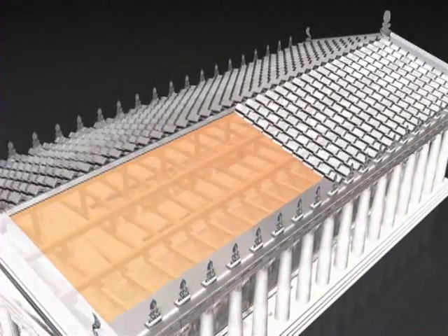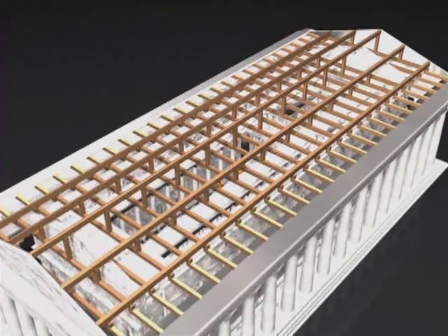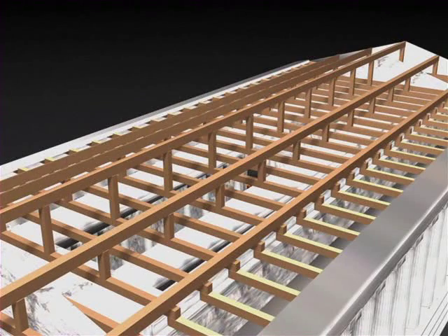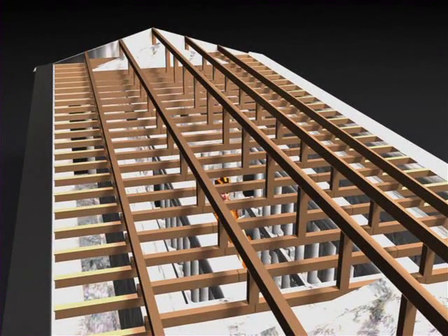The roof was supported on a rather complex arrangement of longitudinal timber beams supported on vertical posts, which in turn were supported on transverse beams that ran across the short dimension of the temple. The correct roof slope was then obtained by varying the heights of these vertical posts. Now, at first glance, this roof system might actually look superficially like a truss, but it definitely was not a truss. The Greeks didn't use trusses, and indeed, the design of their temples was heavily influenced by the lack of a structural element that could span long distances as a truss can. And we'll see more of that in just a moment.